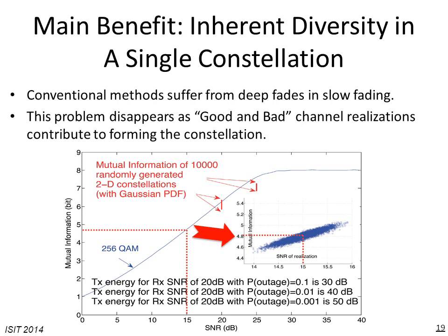So those vertical red lines, which look vertical, are the span of the mutual information of the 10,000 different realizations, which doesn't have too much variation. Essentially, I have plotted the minimum and maximum mutual information corresponding to, for example, 20 dB and 25 dB.